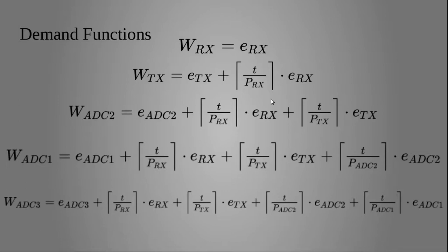So coming to the demand functions for these, we are actually having an arbitrary scheduling algorithm, so we may not have a particular schedulability analysis for it. But we know that the demand function, or basically the time demand analysis approach, is a very general approach, and it can be used for any kind of scheduling algorithm. So these are the demand functions that we come up with for them, and they have been written here, and they follow the similar priority order that we have given.